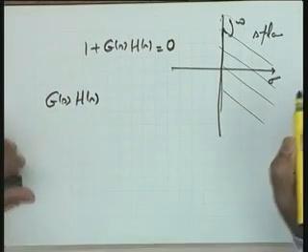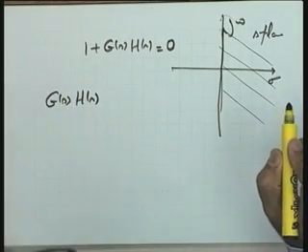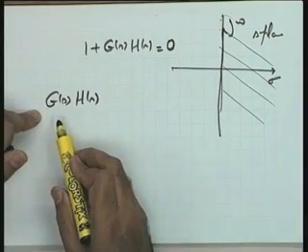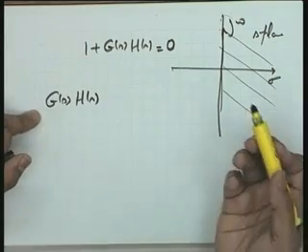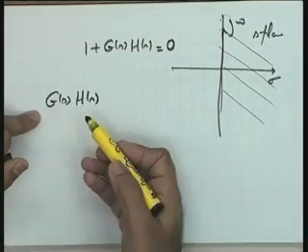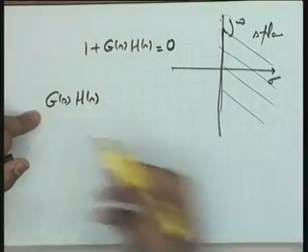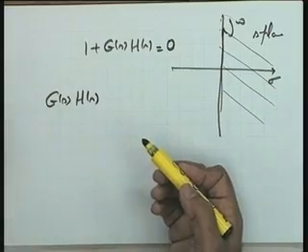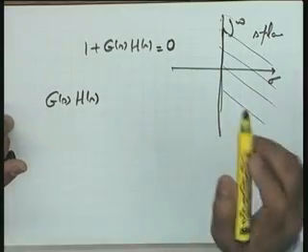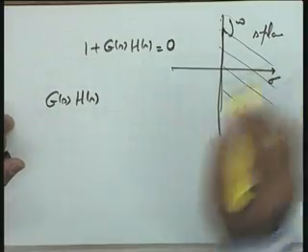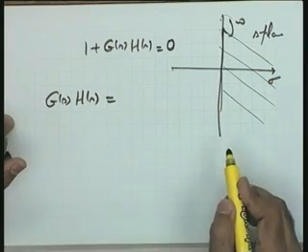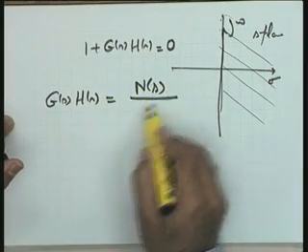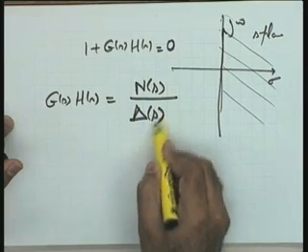What is G(s)H(s)? G(s)H(s) is the open loop transfer function which is known to me. It consists of the process transfer function, maybe the compensator transfer function, the sensor transfer function or any transfer function in the loop, but open loop, the loop is broken. So it means G(s)H(s) is known to me. Okay? So this G(s)H(s), let me assume for the present, is a ratio of two polynomials, the N(s) polynomial and the delta(s) polynomial.